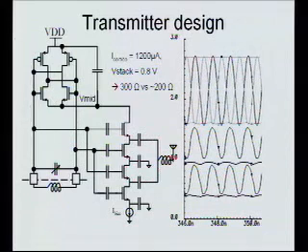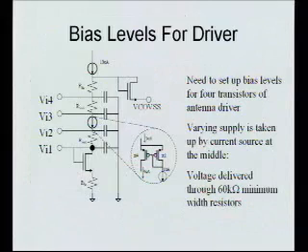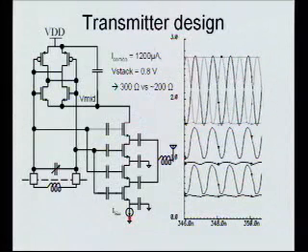So we've allowed ourselves 1 extra inductor here on the antenna, and the idea is it's in series with the antenna. So in principle, you could actually build it into the antenna. If you're having a wire as your antenna, you just make the wire longer and coil it up, and you've got an inductor. And actually, most of the testing we did, we had an explicit inductor in there. So instead of costing 90 cents, we cost $1.05 or something. But it's okay. And the nice thing about that is you use the inductor mostly just to cancel out capacitances. So now you make it real, and then you use the stacking tricks to get the real part to match fairly closely. So, can you do the matching?